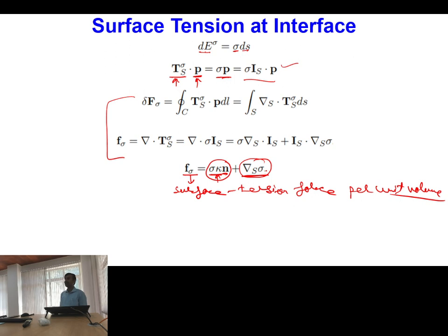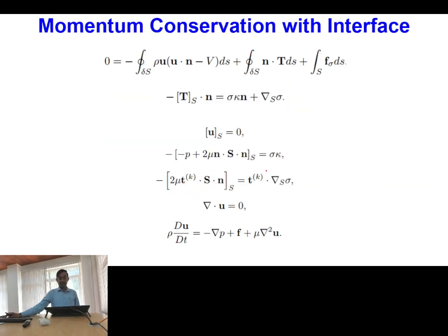You need not exactly know the distribution of concentration at the surface, but by knowing from experience how much change one type of impurity makes in the surface tension, you can give some additional force here, and that additional force can modify or alter your surface tension in order to deal with the contaminated system. So this is the additional surface tension force which we have to account for.